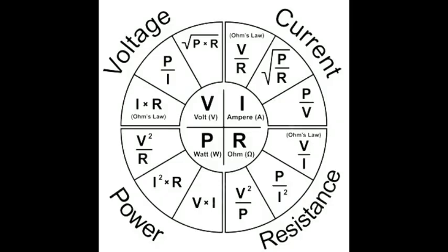No? Not sure? Leo? Well, we have 6 volts across the board, and we got the amperage, so the next thing to do would be to solve for the resistance, for the ohms. To do that, we would divide the voltage by the amperage, so 6 divided by 2 would be 3 ohms for resistor number 1.